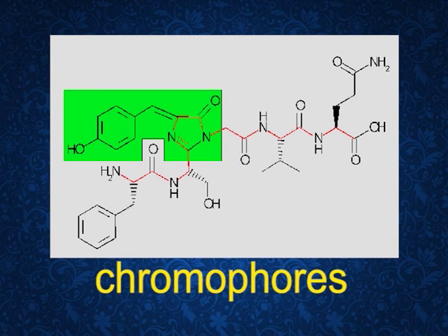When functional groups absorb visible light and appear to be colored, they are called chromophores. Organic pigments are usually brighter, stronger, more stable, have better gloss development, and some absorb UV light, preventing it from damaging the binder. Now come the inorganic pigments. Inorganic pigments are heat and light stable, much cheaper than organic pigments. They are used for specialist purposes, that is anti-corrosion. These are the pigments having improved elasticity and durability.